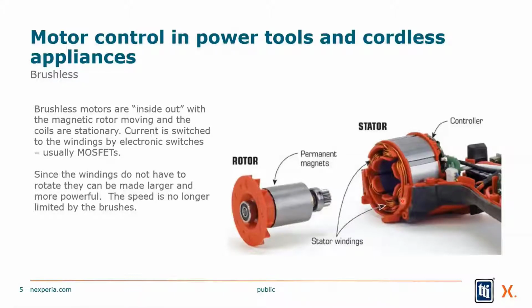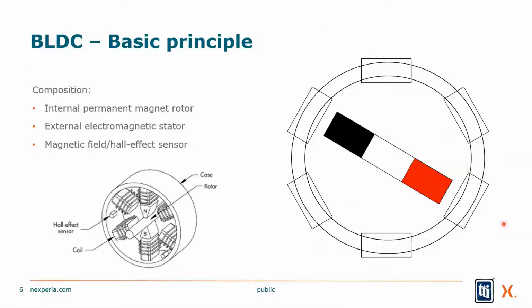One of the marketing buzzwords for these is digital motors, not because they're really digital, but because digitally I control how the electromagnetic field changes, which makes the motor go. All new applications are using these. All the new appliances, white goods, power tools, automotive applications, everybody's moving towards brushless DC motors because you have way more control over the mechanics of the system. The reason we like them so much is this digital section. It requires a lot of electronics, a lot of power electronics, and in particular, power MOSFETs, and that's what we're talking about today.